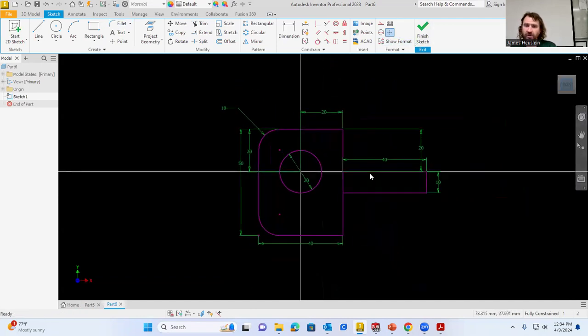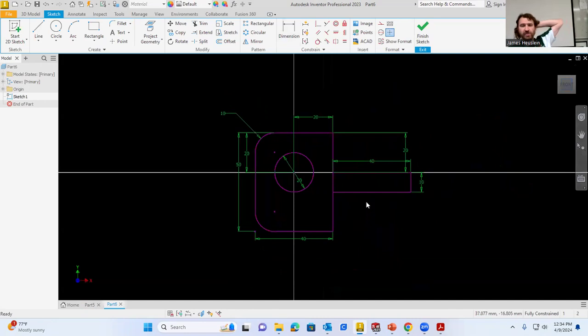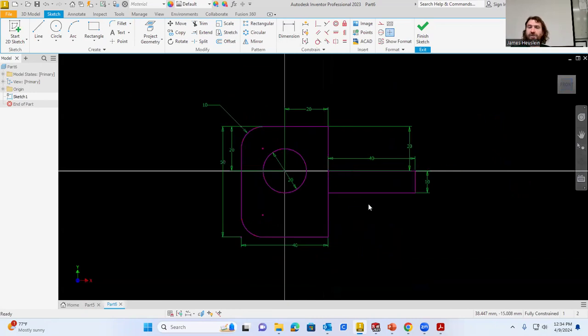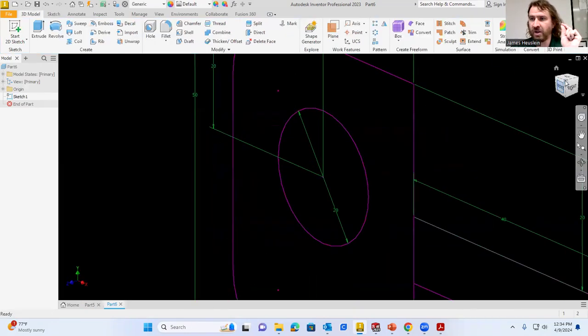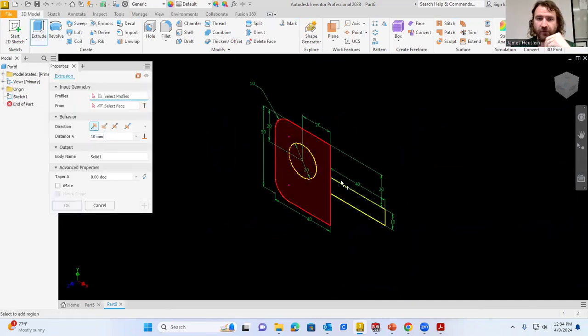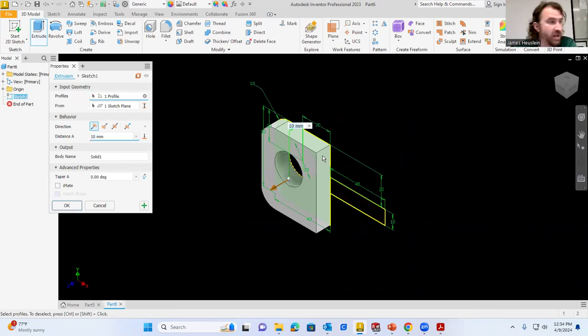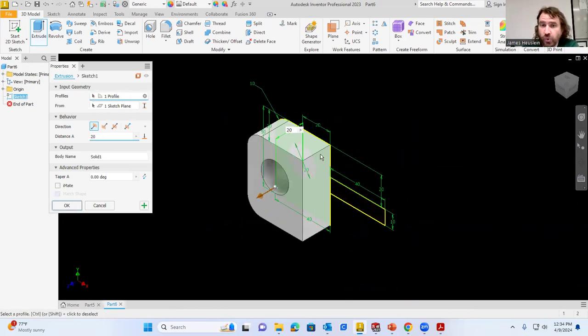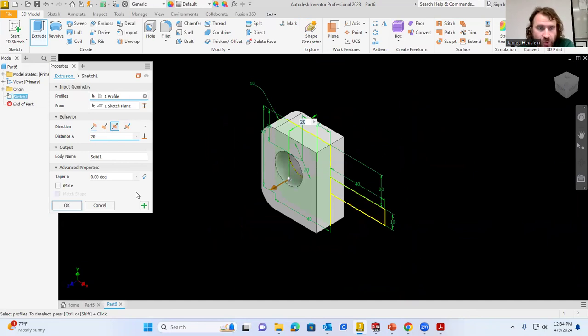Now we're looking at extruding this, but we're going to be extruding this kind of symmetrically in 2 different ways in order to make this part file. So this is the real trick to this particular part file, is the extruding direction and the extruding strategy of how far and what direction, everything else. So if we extrude this profile, this profile is supposed to be extruded 20 millimeters, but we're going to split it. We're going to make it symmetric.